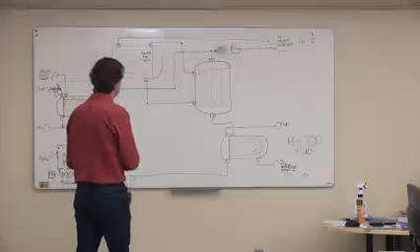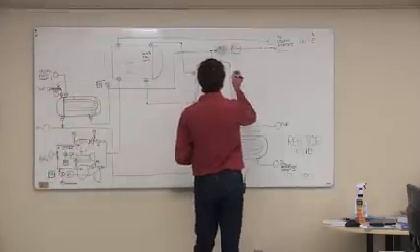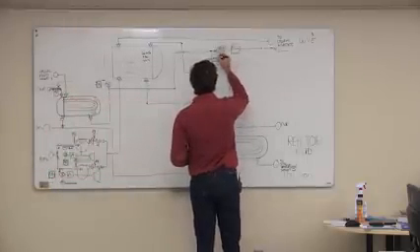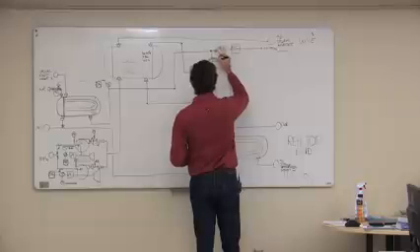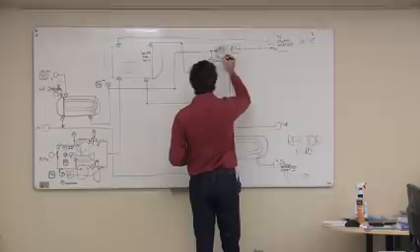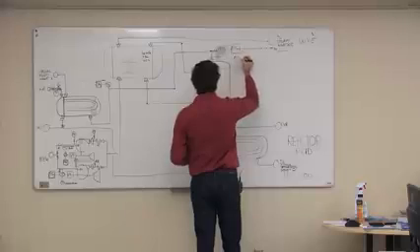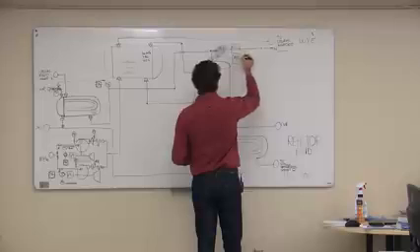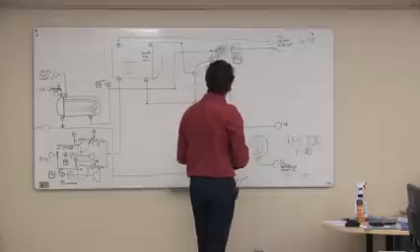So that's that. We might even be interested in what the composition is. So if we have lots of money, we could put an analyzer in on that syngas feed. Put an analyzer indicator in like that. We may not control the process off it, but it might be really good information just to have in the control room.